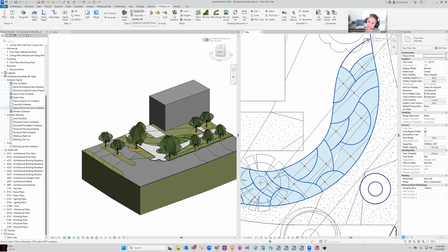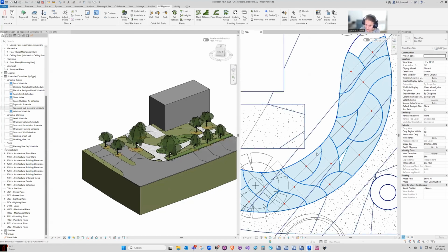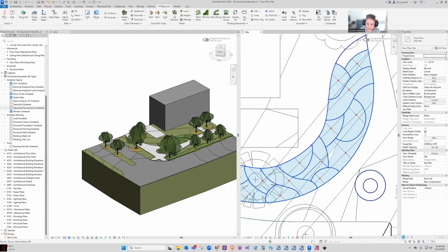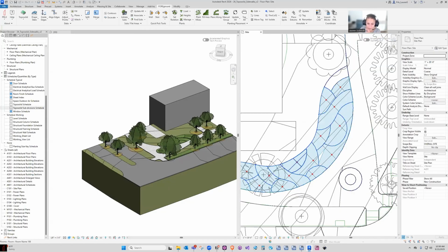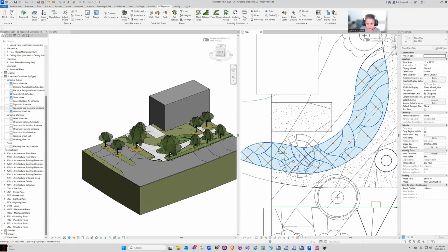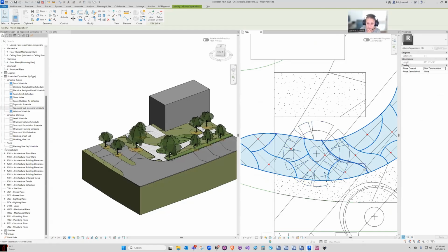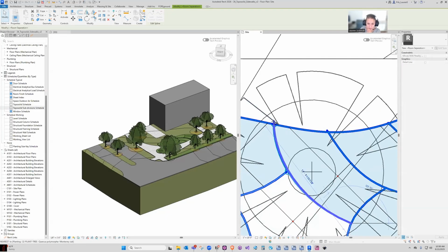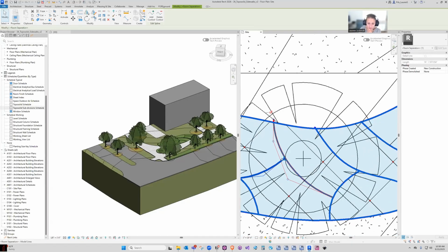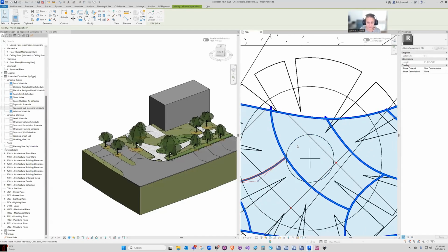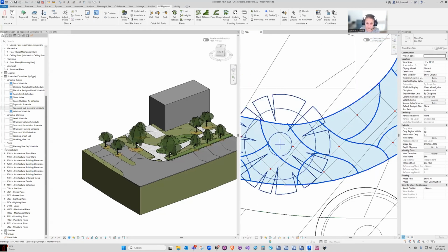If you're familiar with the way I've worked or the way I've taught landscape architects to work in Revit, we will often use rooms or areas for planting areas because they allow you to have an element that you don't have to edit the boundary. Particularly if you ever have planting plans with these fun organic shapes, which some landscape architects love to do, it's much easier if you're not making a boundary every time, if you're just actually using our boundary lines. And you can see these actually behave slightly better when they overlap slightly. Rooms in particular are a little extra funky.